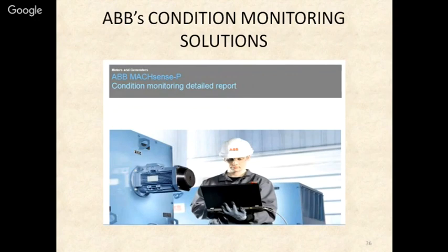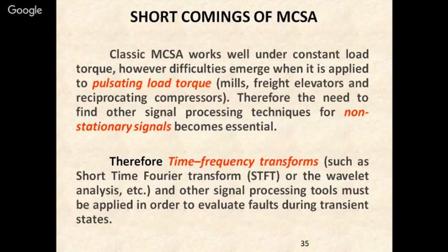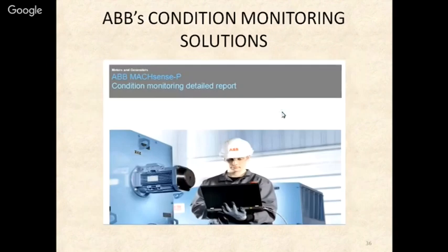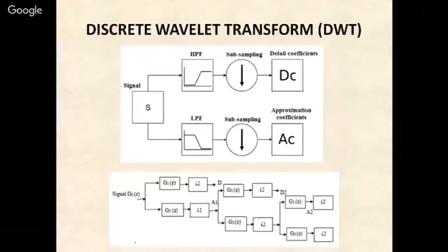However, they are interested in non-stationary signal analysis. That means the case where there is some load pulsation or variation in the voltage of the motor. So in that case, this MCSA method fails.